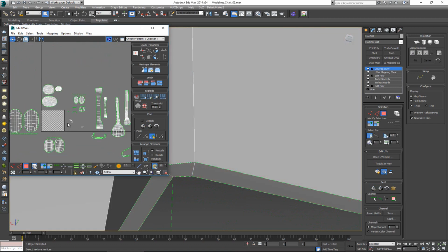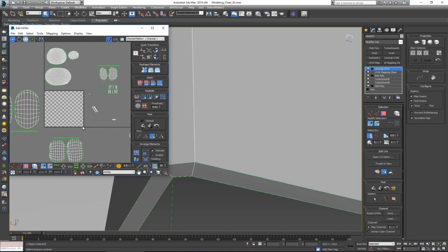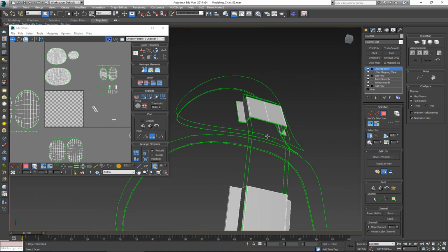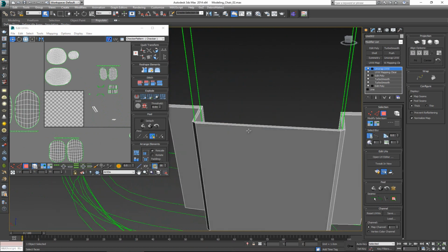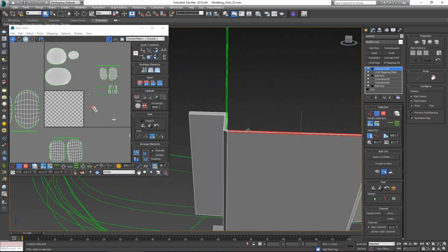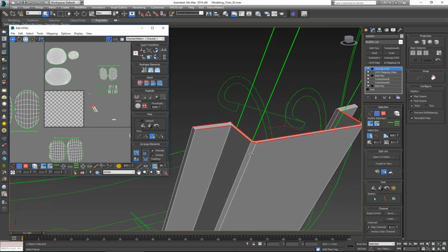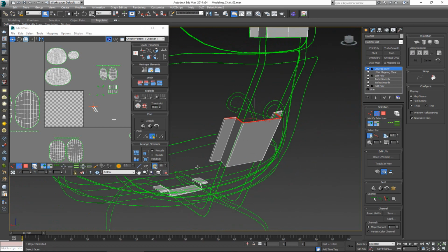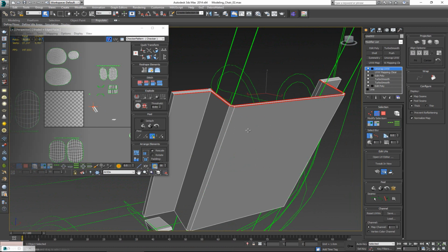And what you're noticing is that I have all of my UV islands scattered across here, and nothing is actually inside the 0 to 1 space, which for now is not a problem, but we will fix that in the next step. So I just want to repeat the same process that we just did for the top one to this part. And I'm going to do this for this piece and the bottom one, and I'll be back with you guys as soon as I'm done with it. No point in you just watching me do this all over again.